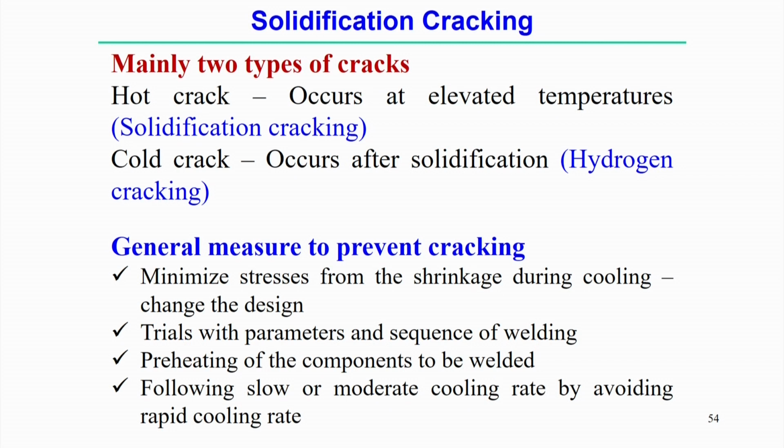There is another significant point to avoid solidification cracking. Several trials with the parameters are required, and then we can find the proper set of parameters that practically avoids solidification cracking, or maybe the cold cracking also. In that case, the sequence of welding may be important.